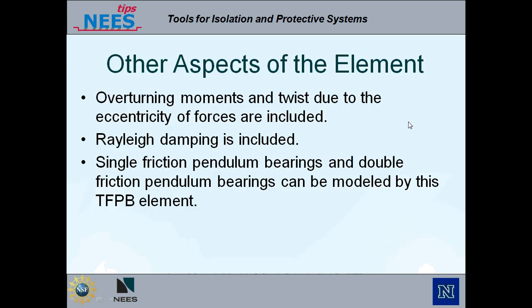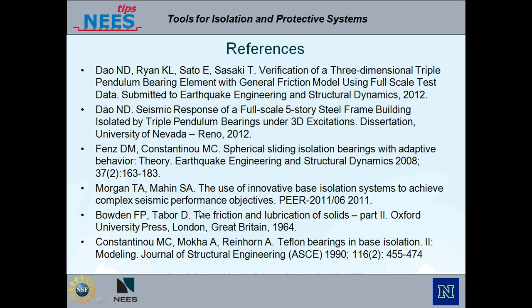These are other aspects of the element. Overturning moments and twists due to eccentricity of forces are included. The Rayleigh damping is also included in the element. Single friction pendulum bearings and double friction pendulum bearings can be modeled by this triple friction pendulum bearing element.